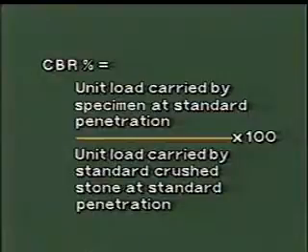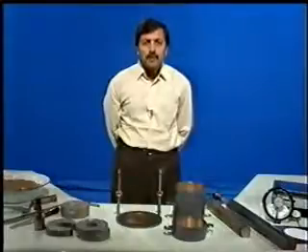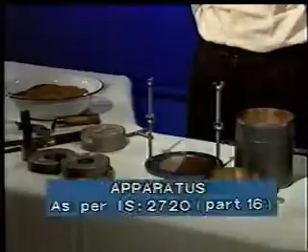The standard material is the one defined as having a CBR value of 100%. CBR value is usually determined at 2.5 mm or 5 mm penetration.